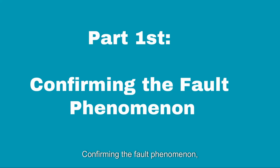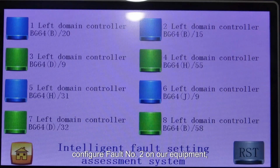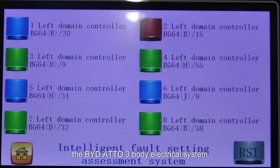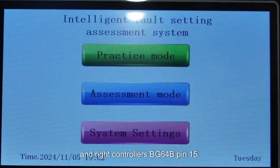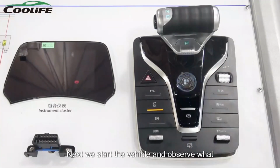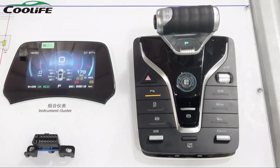Let's get started. Part one. Confirming the fault phenomenon. We will use the fault simulation system to configure fault node 2 on our equipment, the BYD Atto 3 body electrical system training platform, specifically for the left and right controllers, BG64B pin 15. Next, we start the vehicle and observe what fault phenomena the equipment exhibits after configuring this fault.